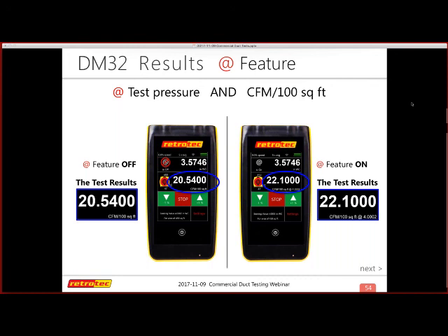The settings are also related to whatever type of unit I've got here on channel A. If I'm using pascals, it relates to pascals. If I'm using inches of water column, it shows up in inches of water column. So it's definitely a direct ratio as a test pressure, but you need to preset that. Most people are commonly testing 1 or 2 pressures, but you do need to go into the settings and do that.